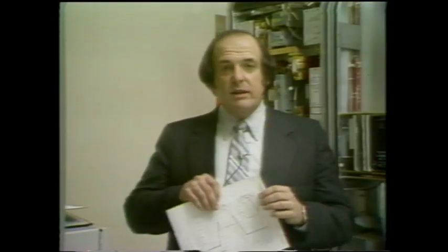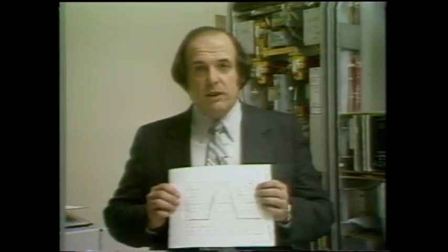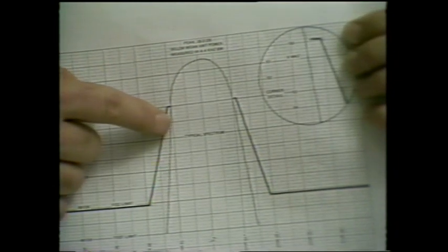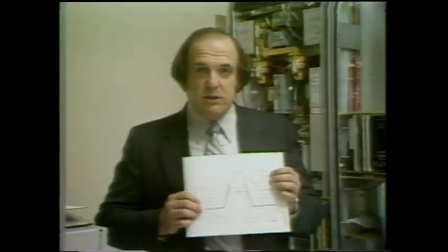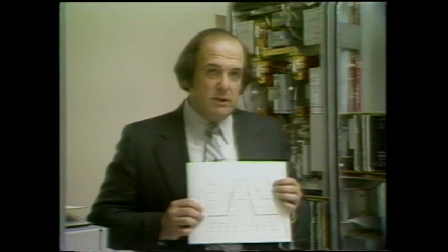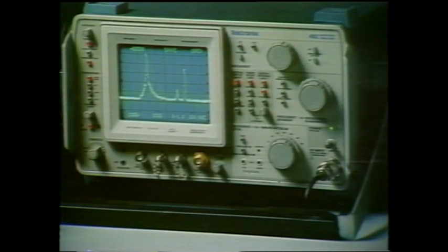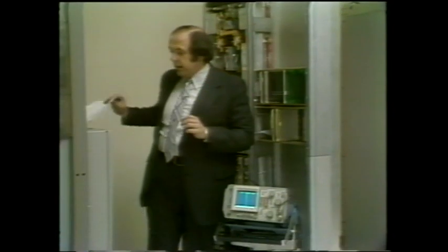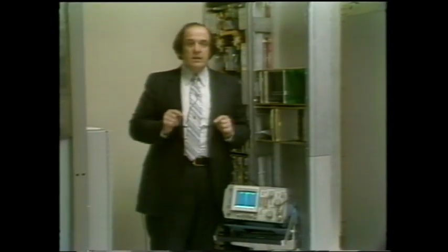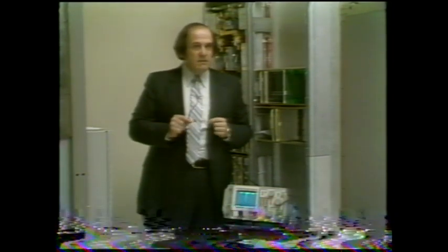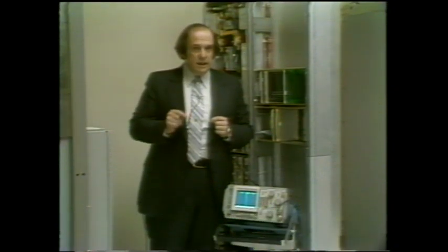I have a mask here that not only defines the FCC required bandwidth of 20 megacycles, but also the point at which the measurement is made. Masks like this are provided with the instructions for a digital radio. We also have a mask that fits on the CRT of the spectrum analyzer. Now, this mask tells you where to make the measurement, but it's different for different carrier frequencies. Radios of 6 gigahertz are measured 50 dB down from peak carrier. 11 gigahertz radios are measured 51 dB down.